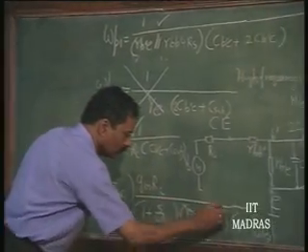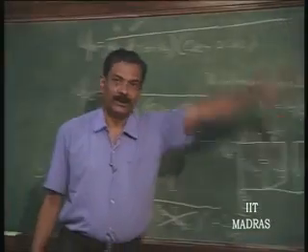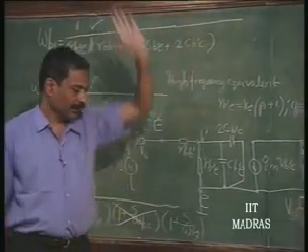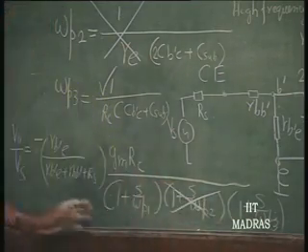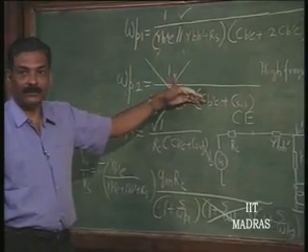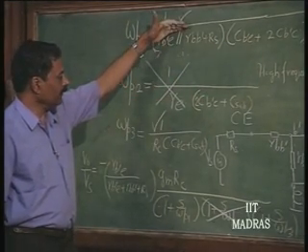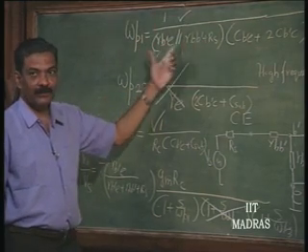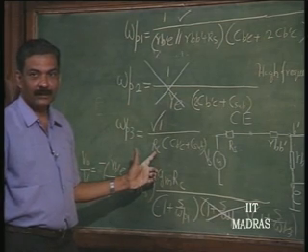So, this pole is of no consequence at all, and it is really speaking a two pole system even now, because this intermediate pole is at very high frequency, at which point the gain might have fallen off to less than 1. So, because of omega p1 and omega p3, the gain fall off occurs. Which one is going to determine the cutoff frequency now depends upon the magnitude of the source impedance as well as the magnitude of collector resistance.